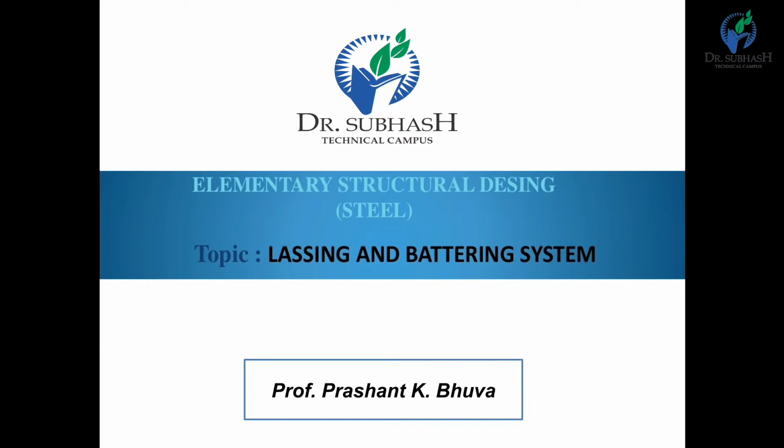This arrangement of a column made of two or more components is called a built-up section. They are generally made of angle, channel or I sections, properly connected along their length. These joints are called lacing or battening.